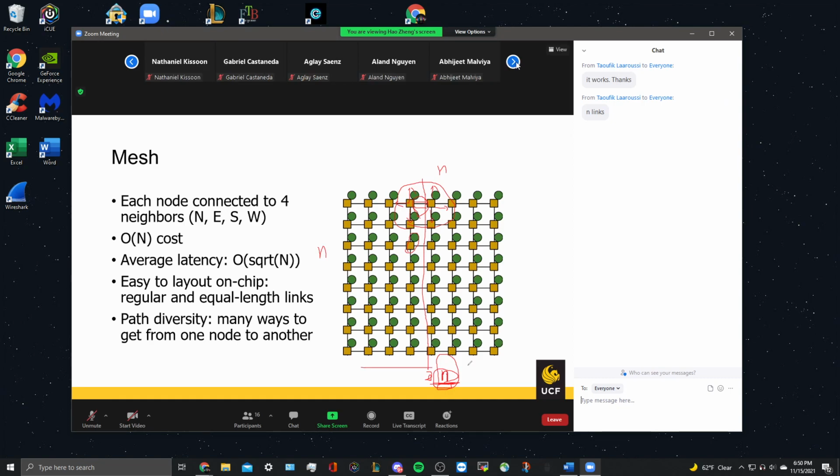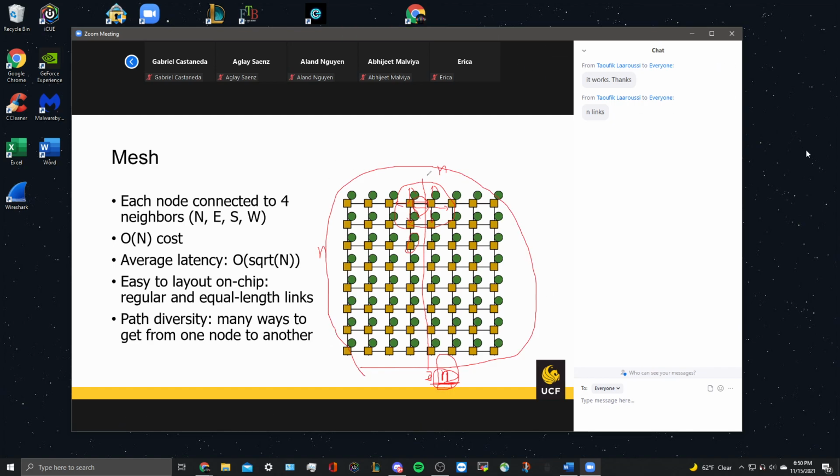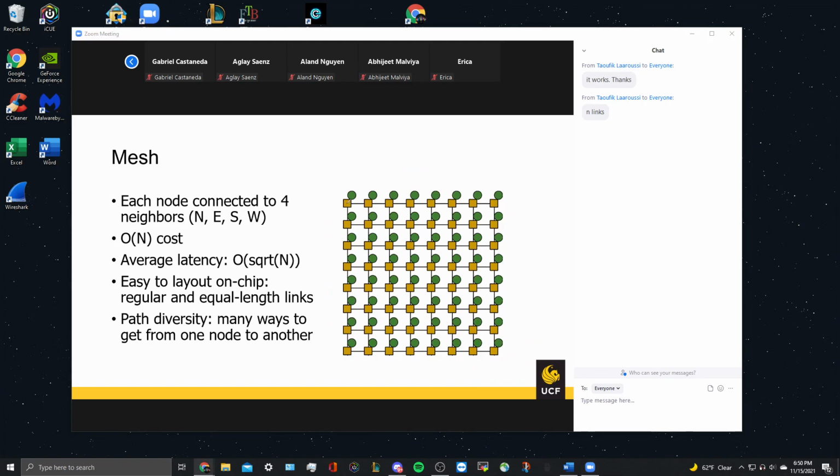And sometimes the high performance processors with 16 cores use this kind of design. But Intel didn't use the mesh topology; they use a kind of ring topology. Let me explain that. You may have these kinds of problems during the interview. So how did Intel design their mesh-like topology? It's mesh-like, but it's not a mesh. They utilize multiple rings.